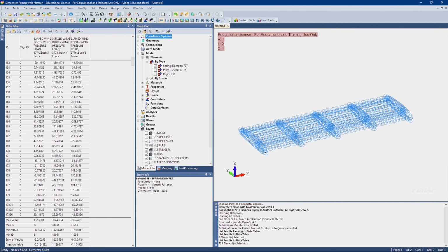Like if you look at these values in the Y column, some of them are almost 0, some of them are 1, some of them are like 200-300 pounds, which is reasonable. 60 pounds, 80 pounds. Here's 50, 200 again, 400. A lot of these are very reasonable values, probably far away from the wing root. Again, those ridiculous 130 KSI stresses that would go away when you properly design a wing root are also going to generate extremely high fastener forces.